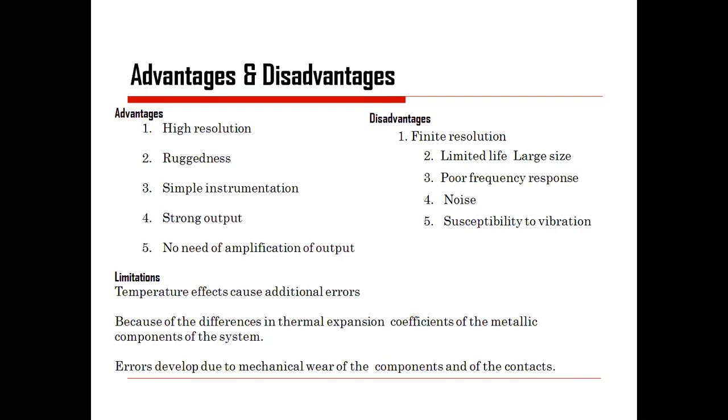But along with this, there are some limitations also. A finite resolution is there for this system. Then there is a limited life span for the larger size, because wear and tear may take place if you are using a rheostat or any connecting type of device. After wear and tear there may be a loss of signal, or an error may be generated.